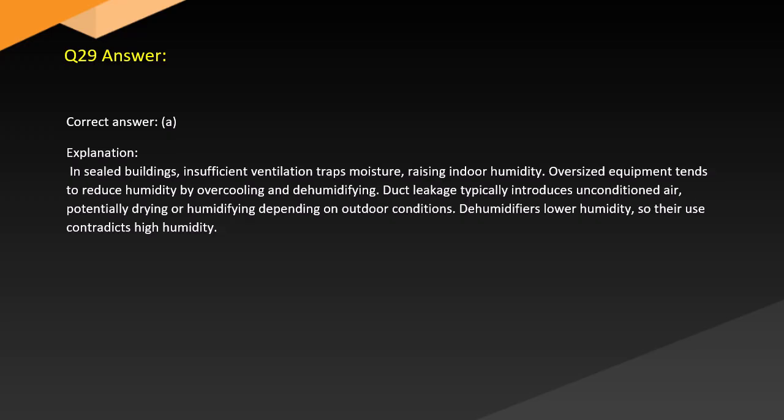Answer. Correct answer: A. Explanation. In sealed buildings, insufficient ventilation traps moisture, raising indoor humidity. Oversized equipment tends to reduce humidity by overcooling and dehumidifying. Duct leakage typically introduces unconditioned air, potentially drying or humidifying depending on outdoor conditions. Dehumidifiers lower humidity, so their use contradicts high humidity.